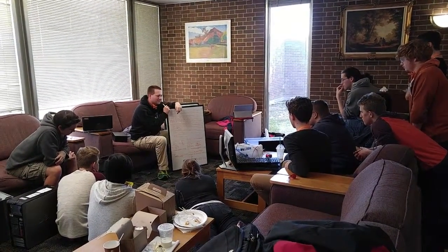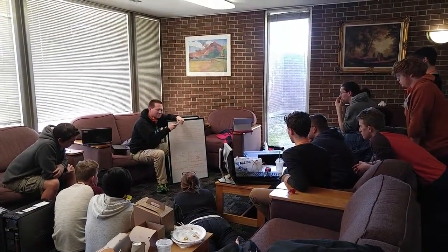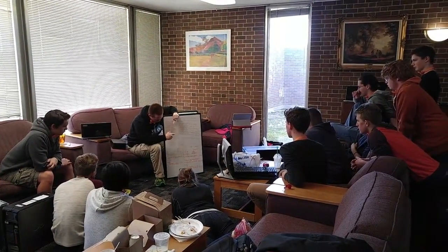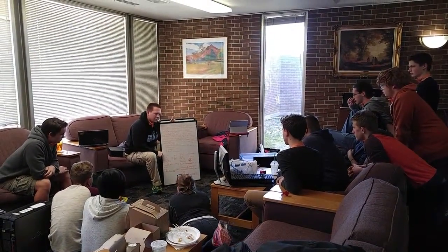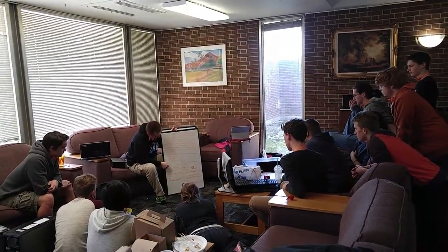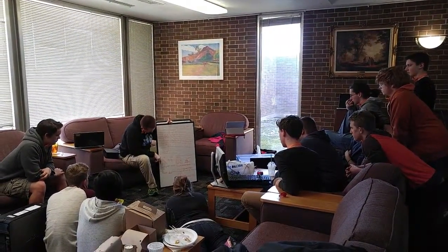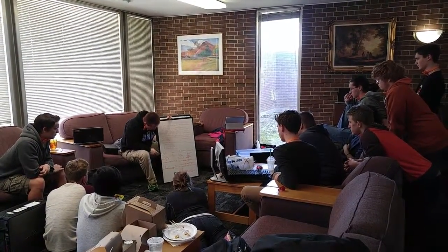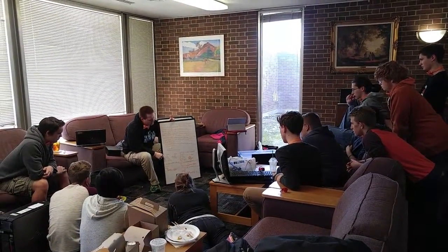However, we also need to consider the coefficient of friction. So to calculate our force, we take the coefficient of friction and multiply it by the mass and by the gravity, because gravity is the force that we need to overcome to push this box forward. So we multiply 0.40 times 400 pound mass times 32.174 feet per second squared, and that equates to 5,150 pound mass times feet per second squared.